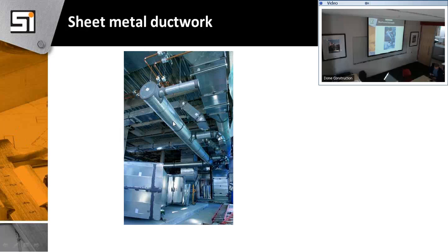So you explain why do you use round duct, why do you use square or rectangular duct? Typically space. Any architects in the room? Architects love high ceilings, and they just try to shove everything up. So they don't allow me the space. I may have a 40-inch round duct, but you're going to see me with an 18 by 60, because most times it's space.